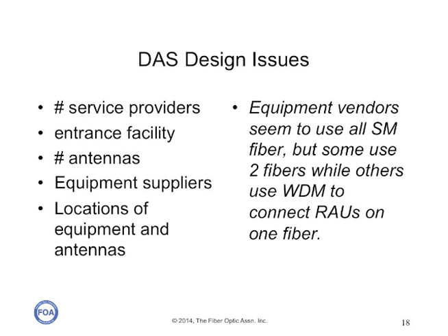There are a number of factors to consider in designing a DAS. Neutral host systems may have to accommodate 4 or more service providers, so entrance facilities must be designed to allow adequate entrance conduits and space for equipment. AT&T recommends approximately 3 by 10 meters space, that's 10 by 30 feet, for the entrance facility, and providing 200 amp service for the head-end electronics.